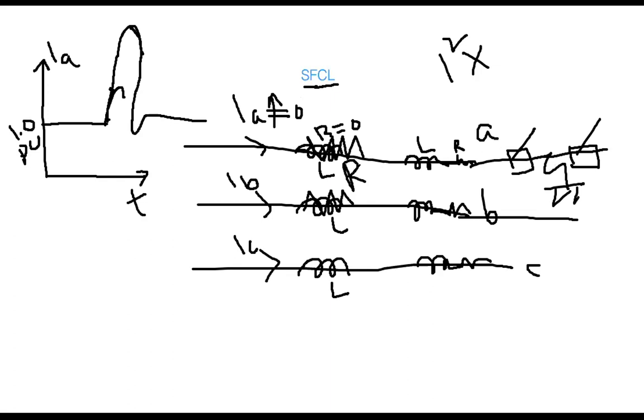But by then this coil has already become non-superconductive because its resistance increased and it got heated up. So even though the circuit breaker opens and no current is flowing, immediately these coils cannot be the SFCL. Assume that your refrigerator is continuously working. Even so, immediately it cannot be a superconductor. You cannot maintain R equal to 0.